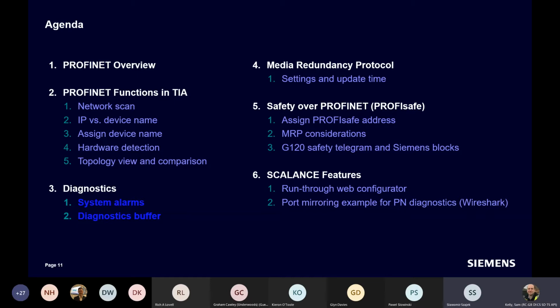So in order to look at the actual status of what the outputs are doing, for instance, you'd probably want to use something like a watch table. Also we have different tools to look at and also force outputs. So if you wanted information on what the individual input is, you would have to have that assigned to a tag and look at that in the watch table.